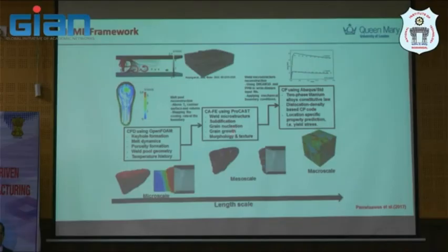So we want to simulate solidification for this problem. In the next simulation phase, we use cellular automata finite element calculation. I mean, this is an early stage. You may know the commercial software package called ProCAST by ESI Group. Quite expensive as well, but this is one of the EU Rolls-Royce projects that I worked on a long time ago. So I just show you an example. We want to simulate the weld microstructures, approximately the solidification, but not in detail like I showed you in the previous lecture, and then the grain nucleation, growth, morphology and texture here.